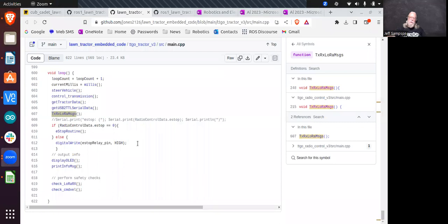You said you don't know if your OLED and all this other stuff is becoming a problem. You could either have a trimmed down version, or trim this down to the point where it's just the radio running, and just send stuff back and forth and see how that acts. Look at the time between received packets and see how stable that is, and then take the code you've got now and look at the time between received packets and see if it acts differently. If it does, then maybe you've got something else in your code taking up time so you don't get back to it.